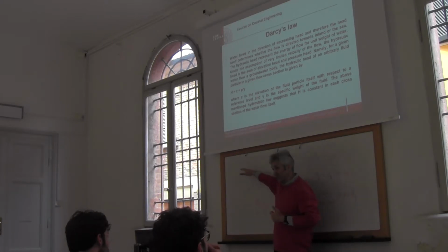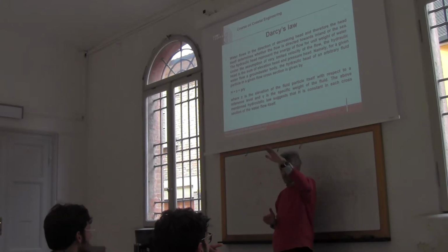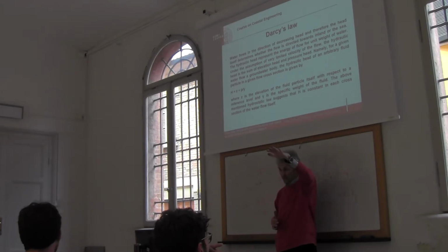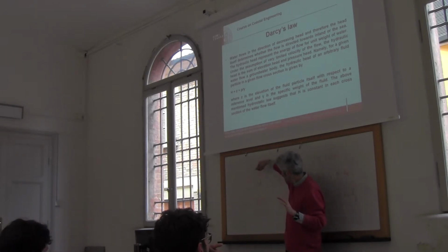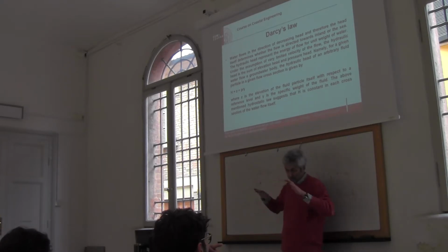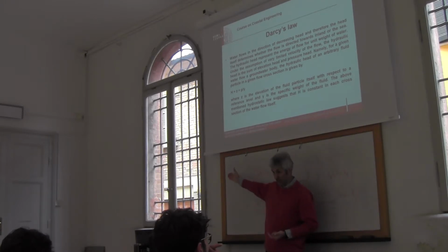While you move inland, you typically get a higher elevation of fresh water. Higher elevation, why? Because the water table typically increases its height while moving inland. And therefore, this is why, moving inland, we obtain the effect of the rising level of fresh water pushing the saltwater interface back into the underground. And therefore, this is why you get a wedge shape. This is due to the increasing level of fresh water.